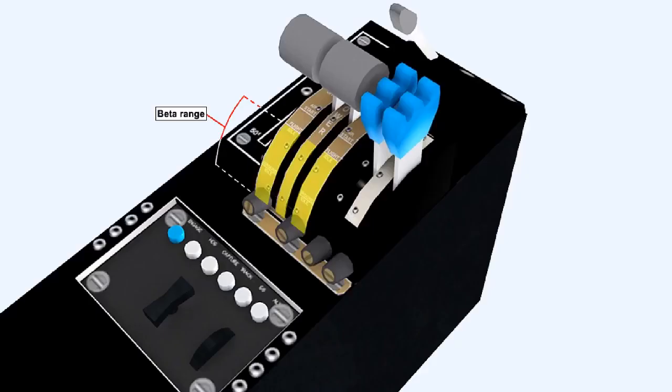The propellers of more modern aircraft may have a much greater range of blade movement in the beta range. The range can extend from around plus 8 degrees to minus 30 degrees pitch, which is full reverse. The beta range of this type of propeller is selected in a similar manner, and at the same point in the landing run as the previously discussed system, that is, during the high-speed initial part of the landing rollout.